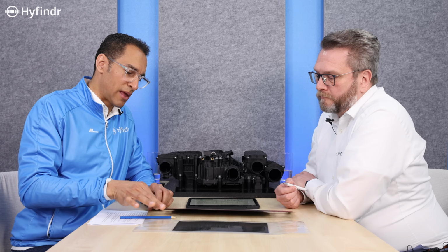Exactly. Plates. Okay. The silicon angle we haven't completely talked about. I guess this is just evolving technology. We also had a video on that one. But great that we've come down to this page. I think the silicon guys say that they are able to do even finer channels on this. It's always the question what they compare it to. Because even in this plate, which was developed together with the ZSW in Ulm, the Hyfindr plate, we have a channel pitch, so the distance between two landings, below 1 millimeter. So we are at roughly 0.9 millimeter in the middle of the channel.